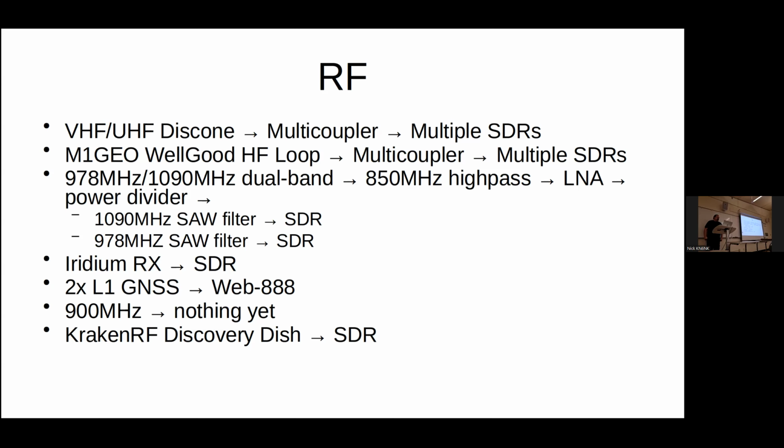What's an ADS-B translator? The aircraft position transmitter stuff. So yes, that one, and it's if it gets really close, like within, I don't know, half or quarter mile and within a couple thousand feet altitude, it takes a lot. I did put an 850-ish megahertz high pass filter in front of that, and that kind of rolls off any local cellular stuff.